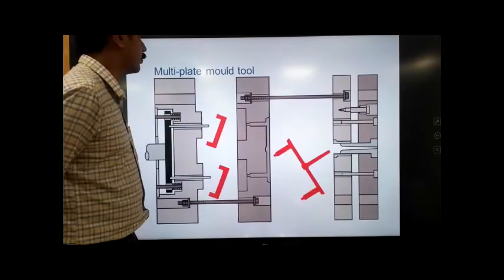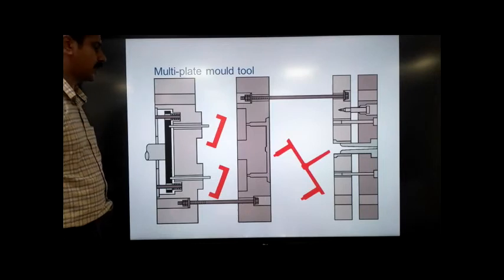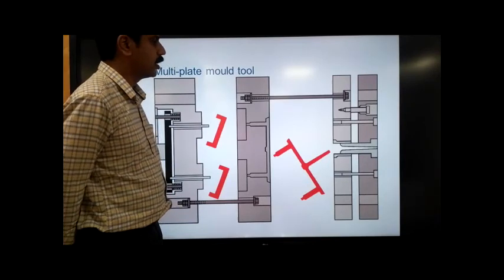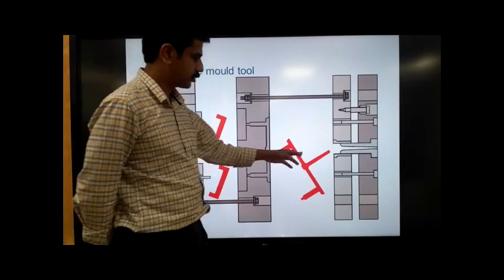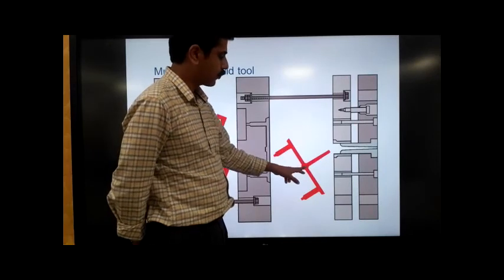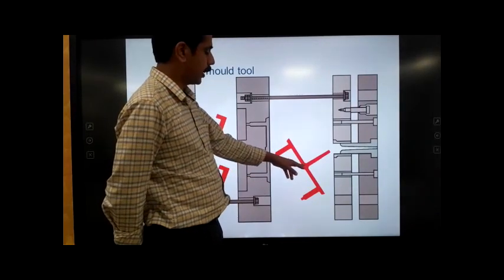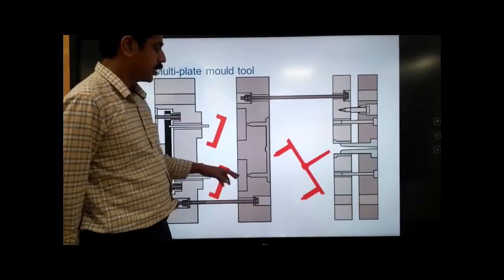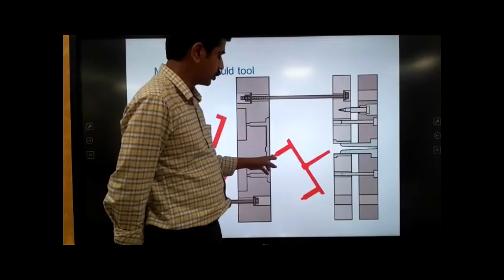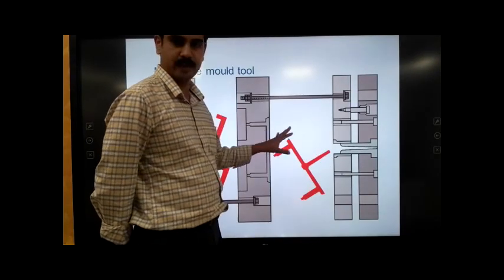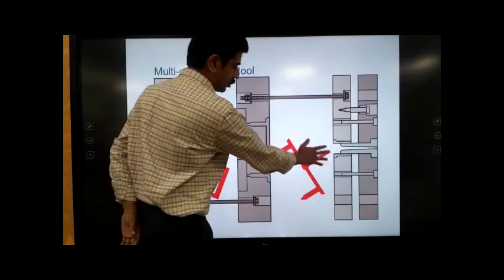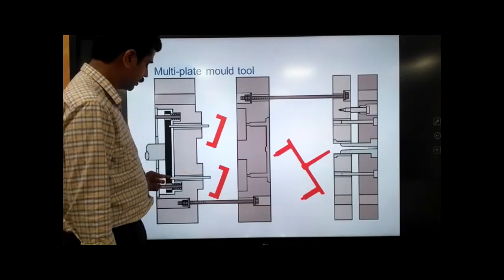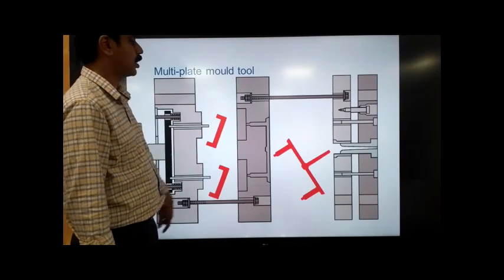This is the molding process, the mold opening cycle. We can see how the operation goes on. This is a 3-plate mold, but still, when the mold opens, it is like this. This is the sprue, and the sprue is connected to the impression. This is the product that we have already mentioned. This is the connecting channel from the nozzle to the impression. The whole system, we call the feed system, as it feeds the impression. This is our product, and this is the pin that comes out. As we already mentioned, the product is out of the mold.